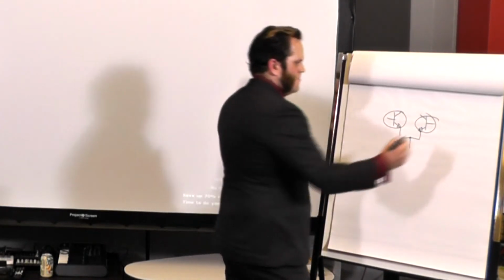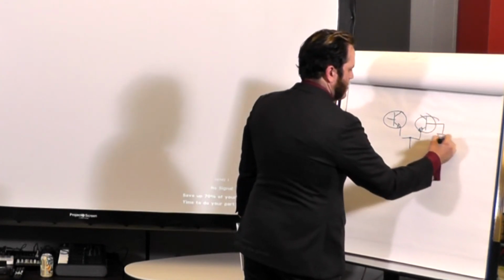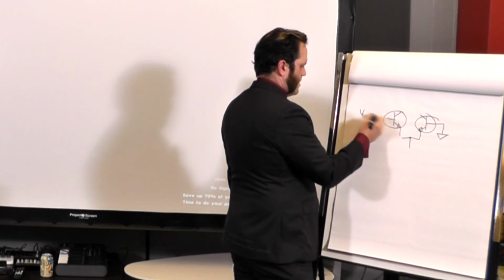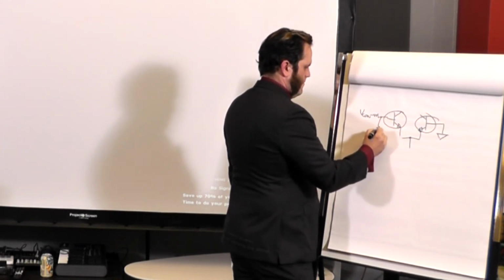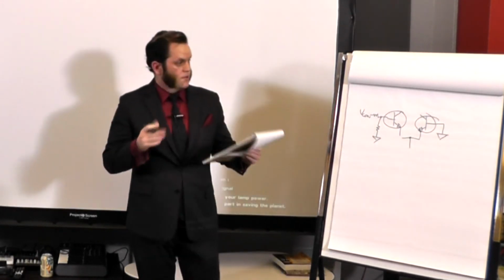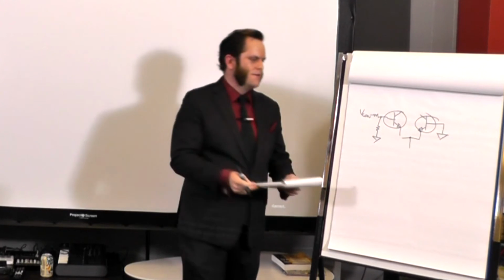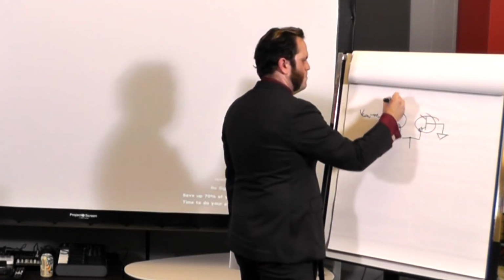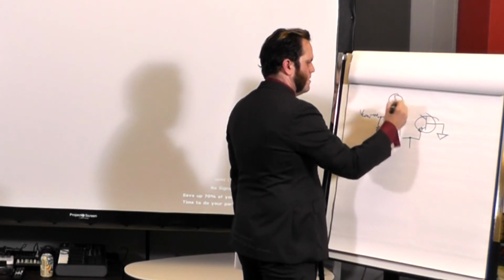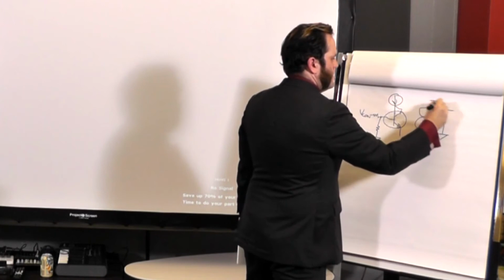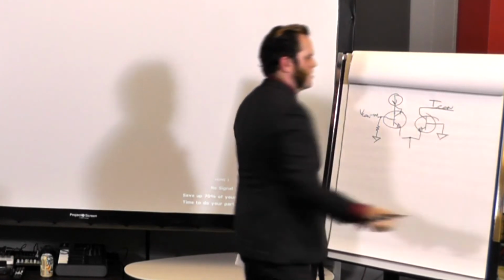But what we're going to do is tie that to ground, and we're going to have our voltage control come in here. Because this is, again, voltage sensitive, we're going to do some stuff. Right, hey, look, we've divided it. So we're going to throw that voltage in there, and that's going to shift the current through this thing for us, and that means if we put a current source up here, and I'll get to how that works in a second, we get our nice exponential control current out there.